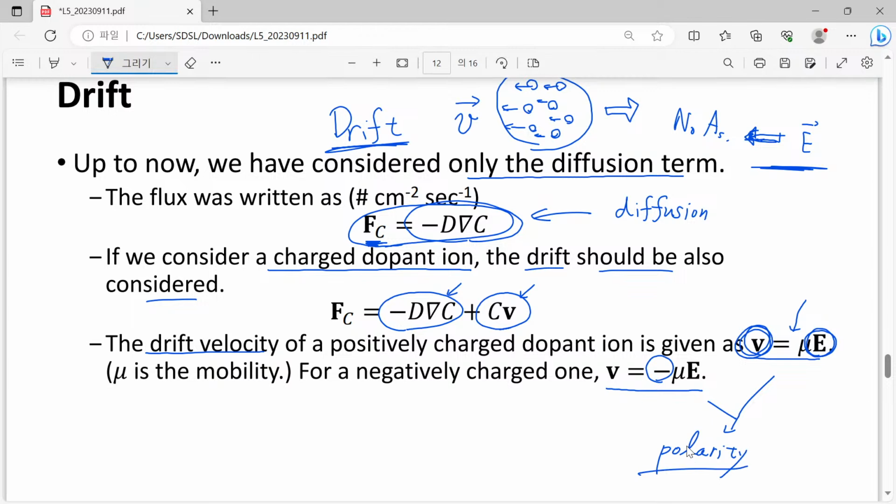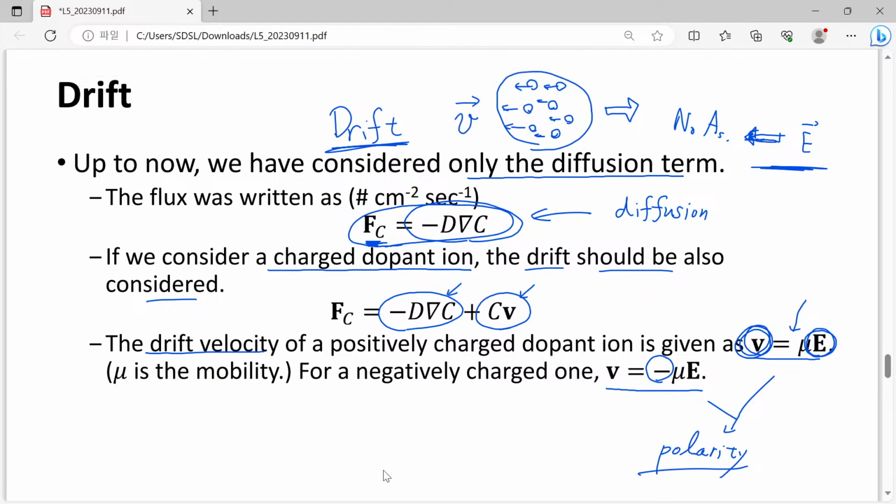So for the same case, let's say this one. Here we have arsenic and also the same amount of boron. Here arsenic and boron, and we have the same electric field. What will happen? In this case, the movement of our arsenic will be reduced, lower diffusion. And how about our boron? Their movement will be enhanced.